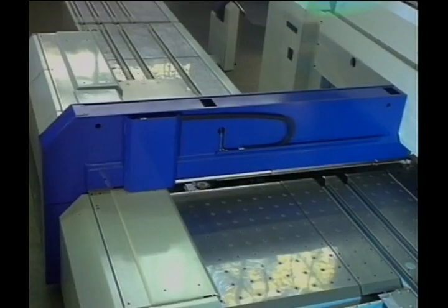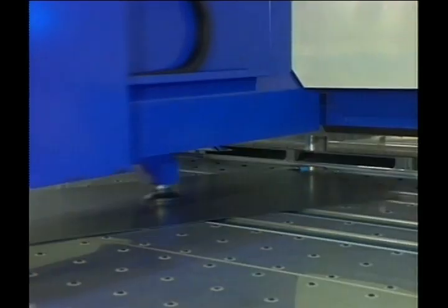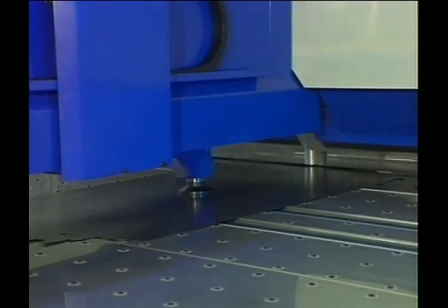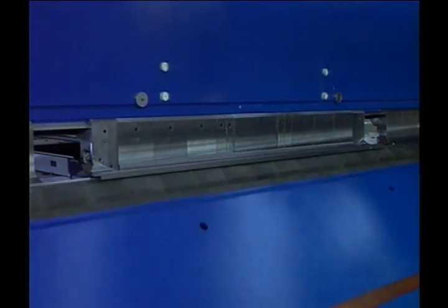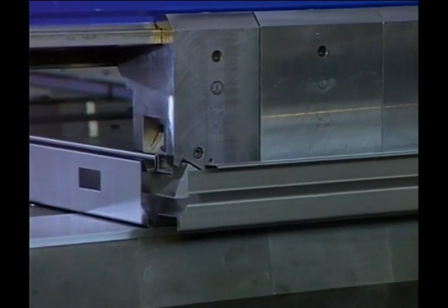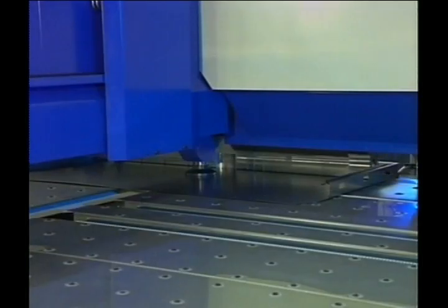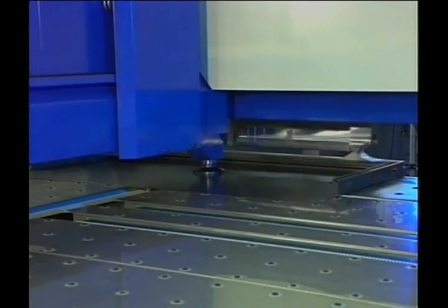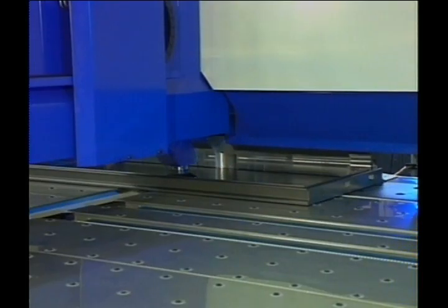Folding is another process used to bend parts. A folding machine consists of an integrated sheet support and gauging system that feeds raw material from the rear of the machine to a set of upper and lower clamping jaws. Once the workpiece is positioned and clamped, a folding beam sweeps upward, gently creating the desired bend angle, anywhere between 0 and 180 degrees. Folding machines are especially suitable for large or complex parts requiring multiple bends, such as metal doors and furniture, electrical enclosures, lighting equipment, elevators, and conveyors.